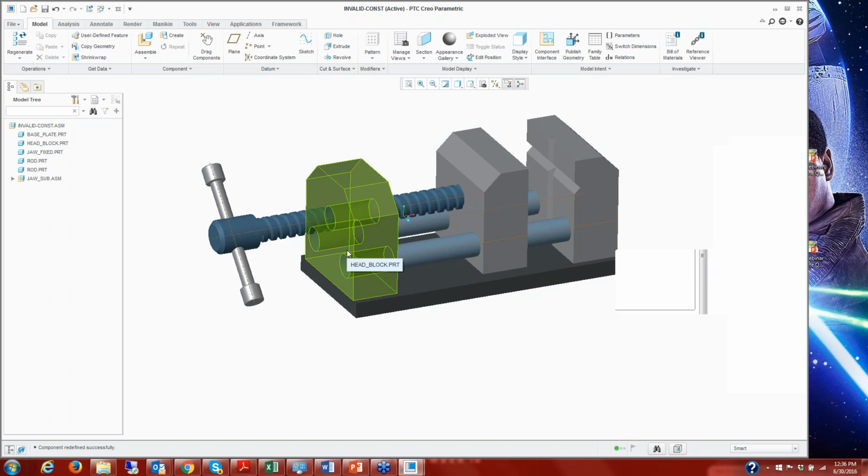The displaying of the missing references, where when we did the one with the ribs that we saw the references highlighted for the missing references, that is new to Creo 3. And remember, that only works if the model has been regenerated in Creo 3 successfully at least once.